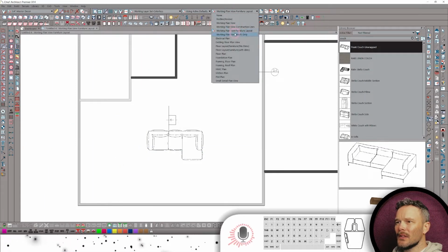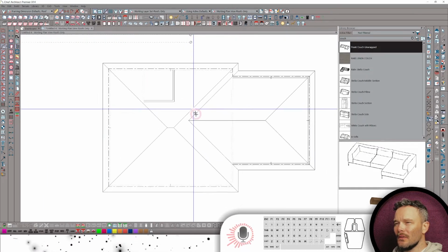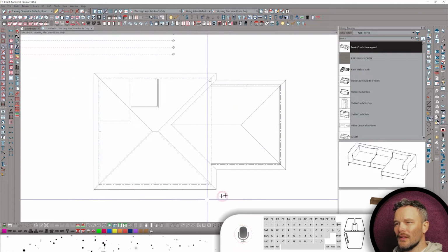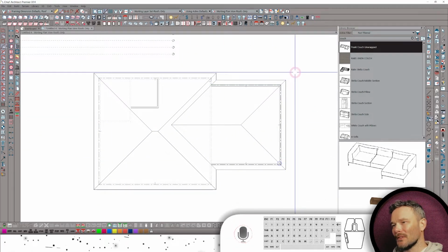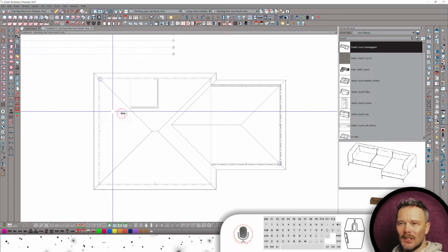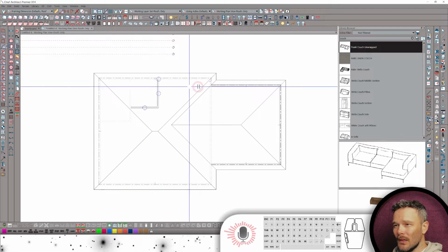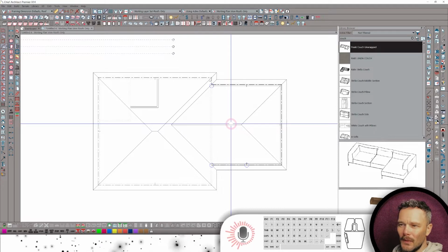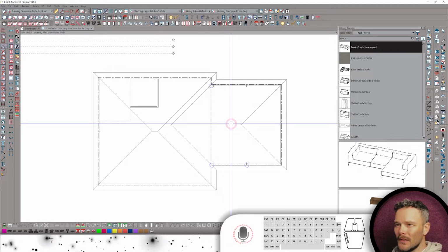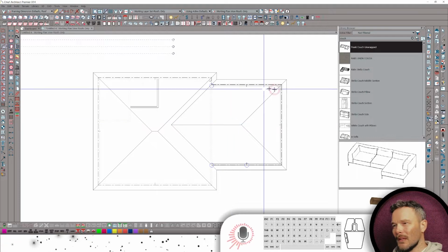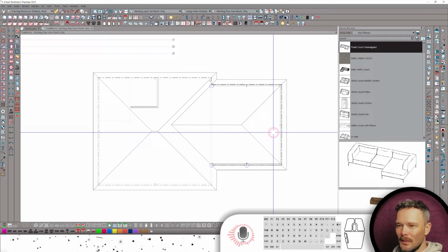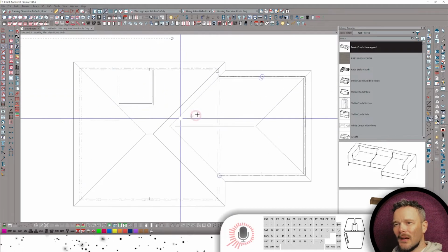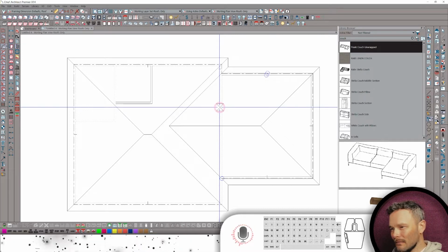Let's go ahead and switch to working plan view, roofs only. You're going to see we've got auto roofs turned on by default. And what that means is it's just showing us, well, for one, it's showing us our new walls in kind of a bold section. And that's helpful if I really want to line some new versus existing roof planes up with my new walls, or maybe I'm paying attention to bearing walls. But this is where I need to do my manual roofs if I need to get into that.